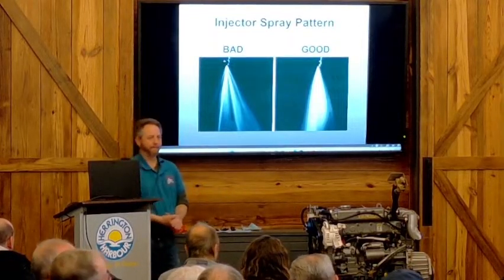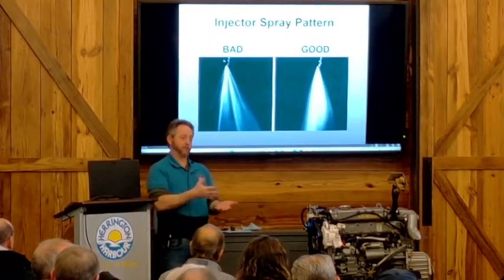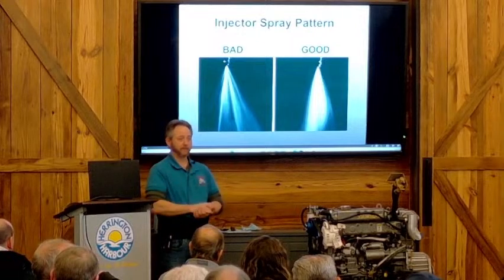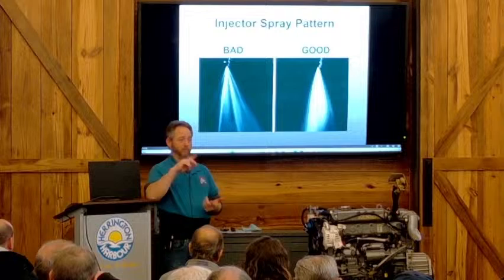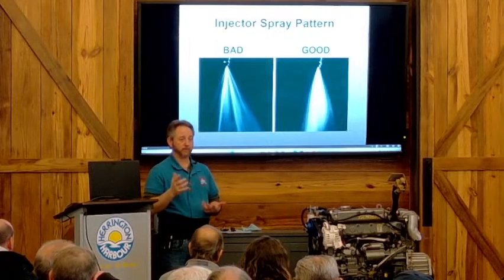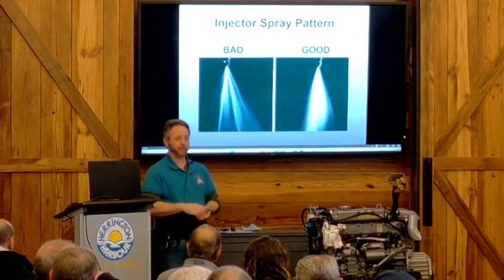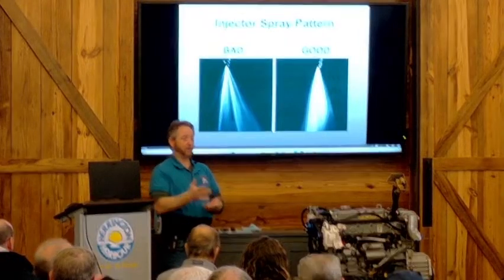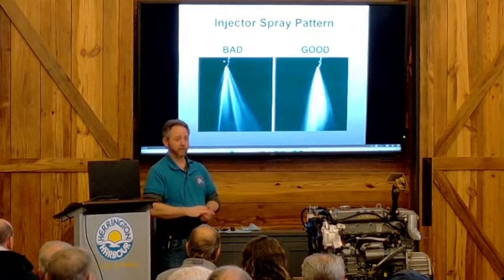Is that something an engineer or boat owner could do, or would you just? Well, you need a special tool to actually rebuild them, to test them. Yeah, you can pull them apart and put new tips in them, but you won't know what pressure is required to make that spring compress, so you need a tool to check that. But yes, you can pull your own injectors out and drop them off or send them to an injection shop.